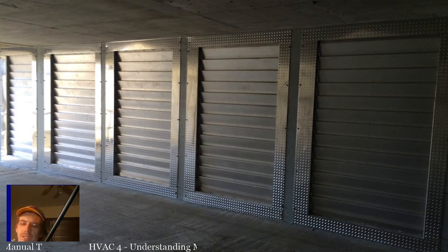They will be at such low levels that it's most likely safe in most instances, but those need to go in well ventilated areas. So typically, especially with infrared heaters, you're going to see those non-vented types in things like repair garages and things like that. Something that's already well ventilated, where you have large doors open a lot of the time, so that the venting isn't a concern, really. That's something just to keep in mind.